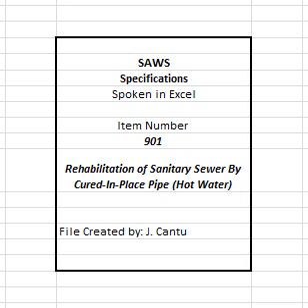5. Access pit location. A location and number of insertion or launching pits will be chosen by the contractor and approved by SAWS, and will typically be located at or near existing or proposed manholes or junction boxes, points of intersection, PI, in the line, at logical breaks in the construction phasing, or at locations to comply with access or maintenance requirements.